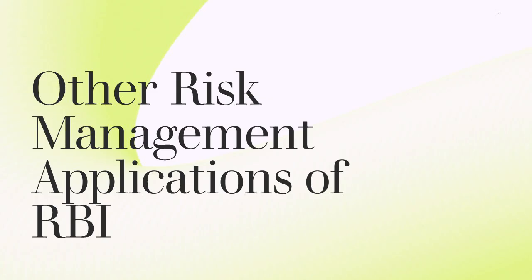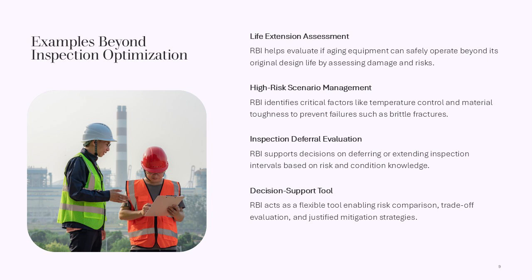Examples beyond inspection optimization. Beyond inspection planning, risk-based inspection provides valuable insights that support a wide range of risk management decisions. One important application is life extension assessment, where RBI is used to evaluate whether aging equipment can continue operating safely beyond its original design life. By understanding damage progression, remaining life, and consequence severity, engineers can determine whether continued operation is acceptable or if replacement is required.